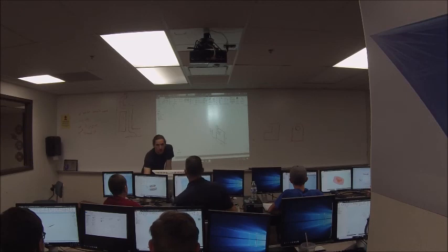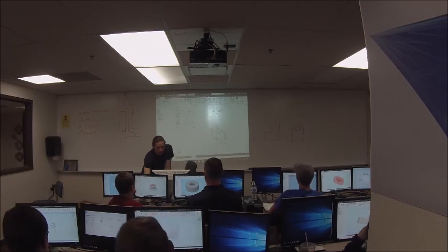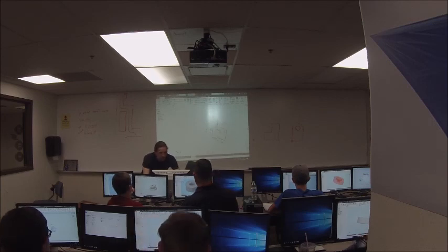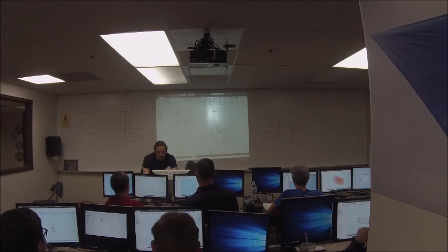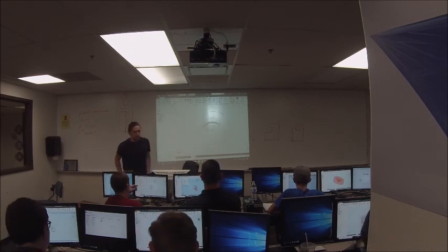Okay, so Micah, here's what you did. Austin, you too. You click revolve, you click your profile, and then when you click your axis, you picked one of these side lines. Right, like Micah, I think you did this one. You should click this line for your axis. Select your region, click axis, and then click the line. That'll give you the little line that comes off the origin.